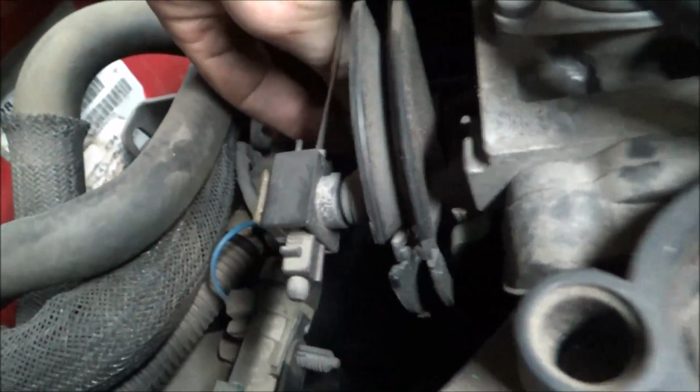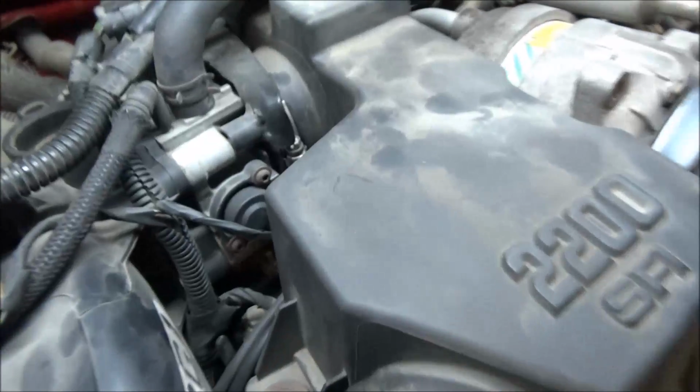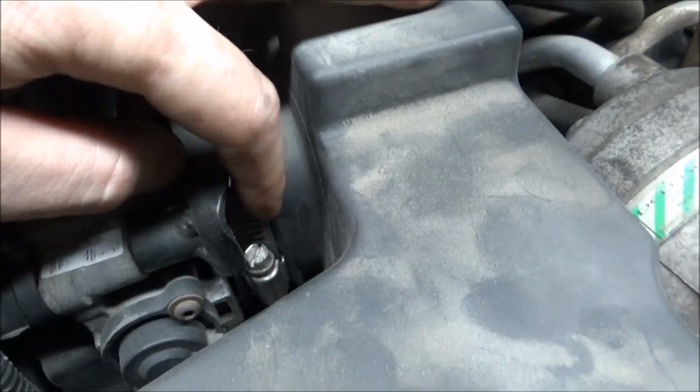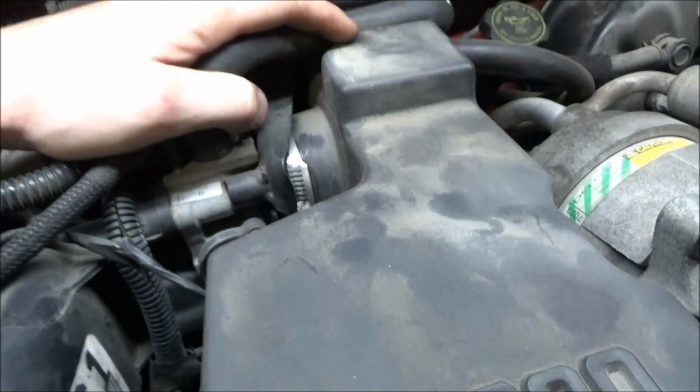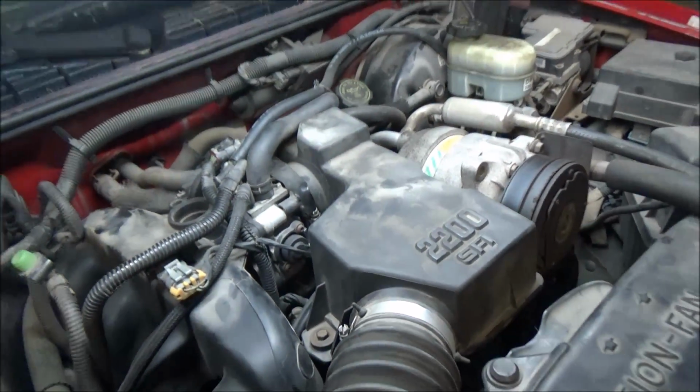Comes right back here. I'm touching it with my hand. It's kind of underneath this throttle plate right here. It just hooks into the back of this air box, guys. No big deal there. And then if we look directly at the throttle plate, we also have this last hose clamp. So I'm going to get you guys set up, and I'm very quickly going to whiz this unit off of here so we can access this throttle position sensor.